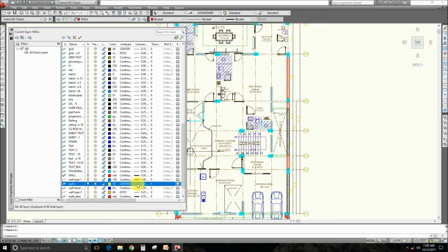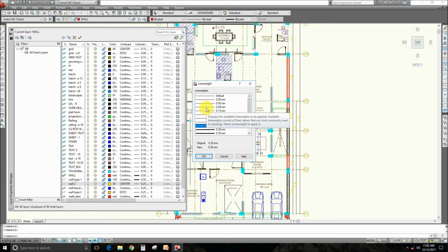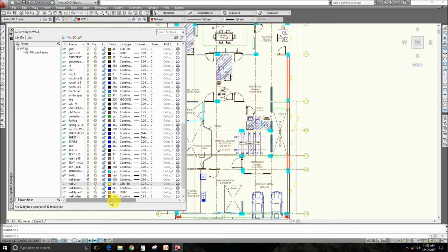One more thing, line type is very helpful to show different gradations on the plot and it will look nice. I will show you an example of it. If you want to lock your layer, this is how you can lock it. And let me tell you one thing, if you are locking your layer, it means you can't make any changes to this layer, you can't move it, you can't delete it, etc.